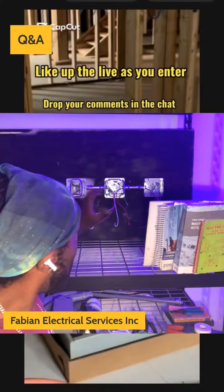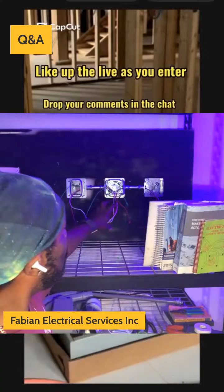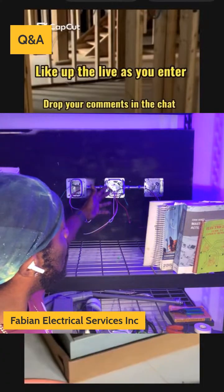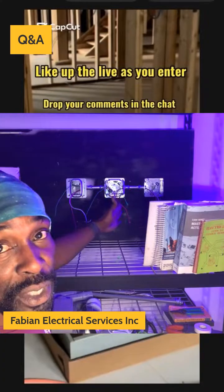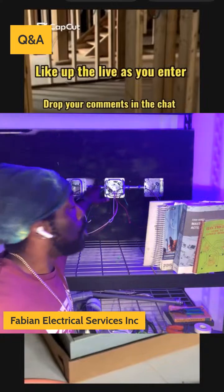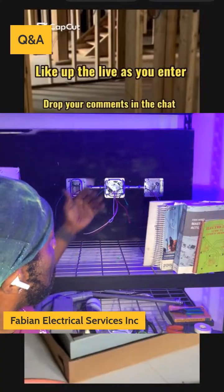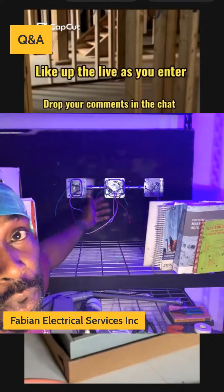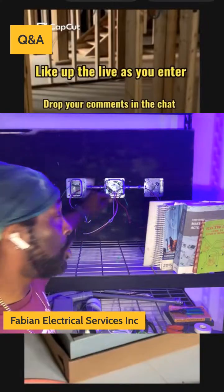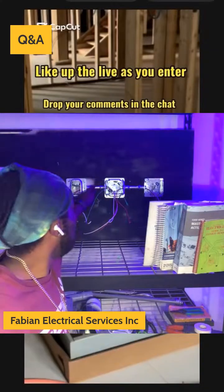Again, every wire that comes into your box and you make your connections with is going to count. And again, let's say you have 5 wires coming from this side and 5 sets of wires coming from that side. Obviously your pipe also has to be equipped for the code to allow the minimum number of cables entering this box. So you not only have to rely on this box, you also have to rely on your pipes.